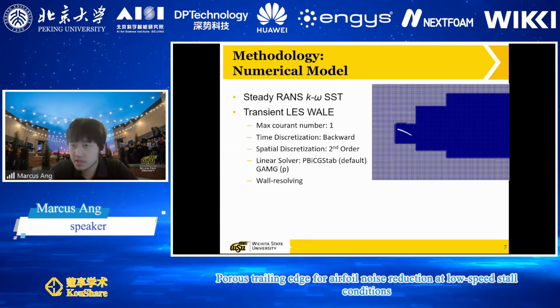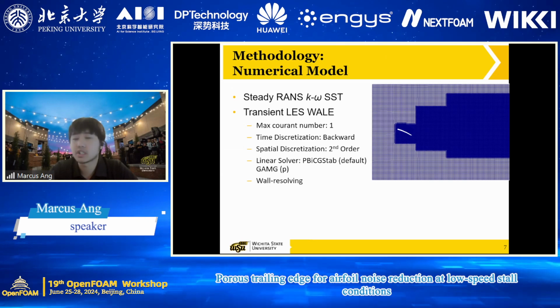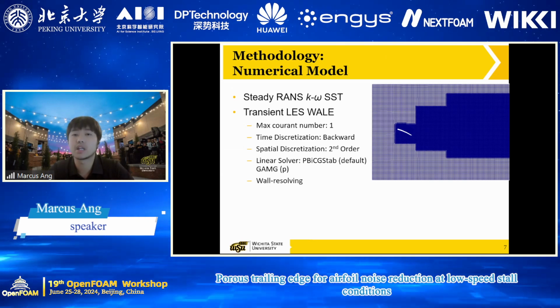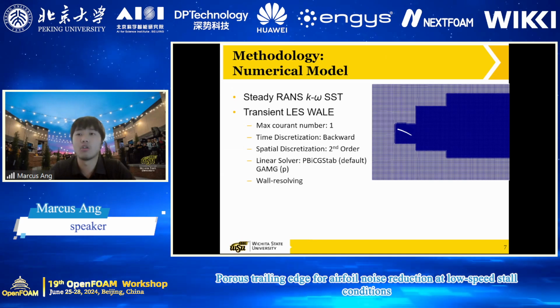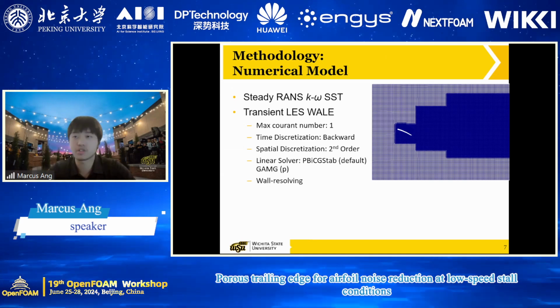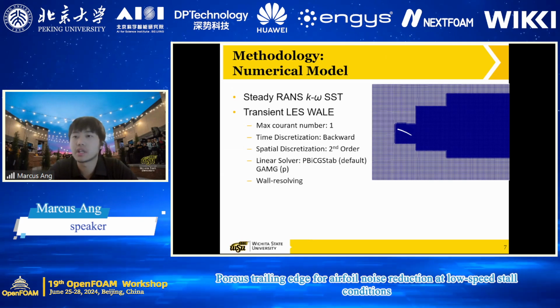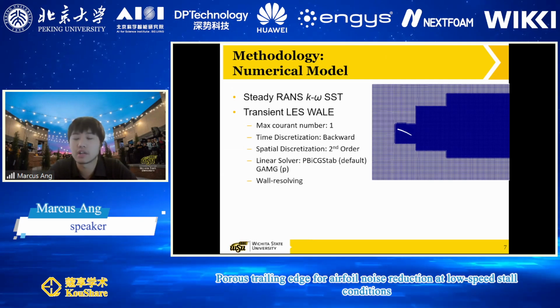The mesh is wall resolving, and because of the porous media, we're going to be using a pore scale approach, which basically means that we're going to resolve all the little pores within the airfoil. So we're not using a Darcy-Forchheimer kind of model.